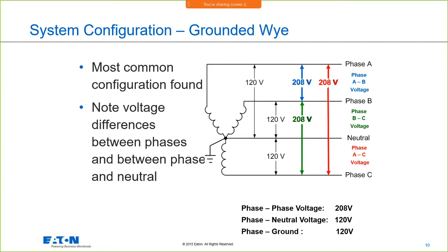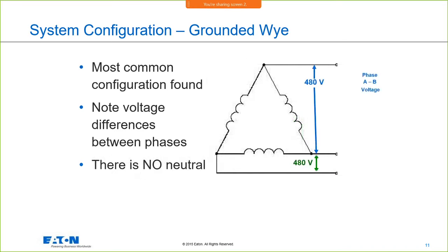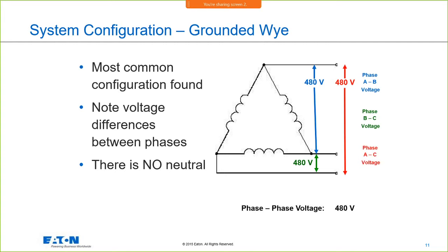So the voltage potential does make a difference in the interrupting capability of that circuit breaker. You'll have different interrupting capabilities based upon the voltages, and we'll talk about that when we get into interrupting. But I have to make sure that I apply my circuit breaker correctly. And this one here, these types of systems, they're 480 volts, straight 480 volts. I have to make sure that I have a straight rated circuit breaker in there that's rated to handle 480 volts.